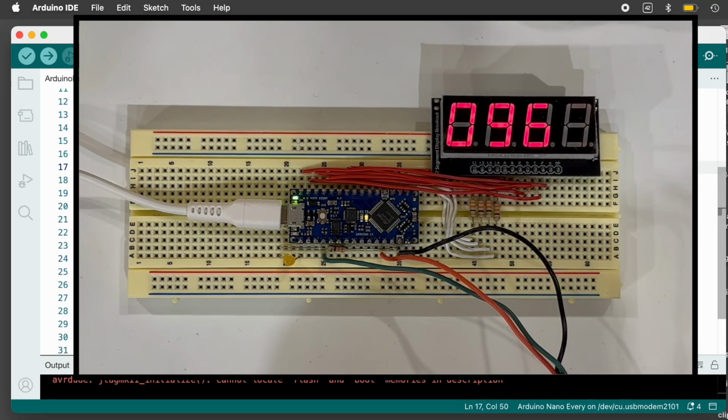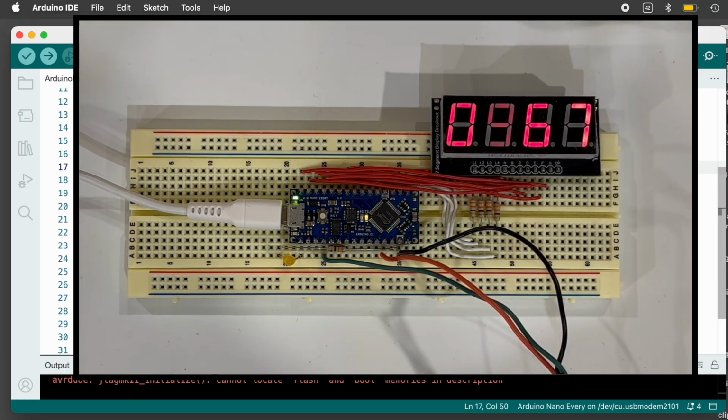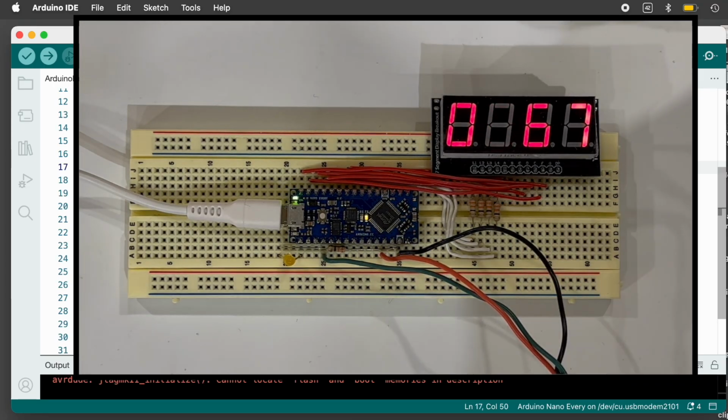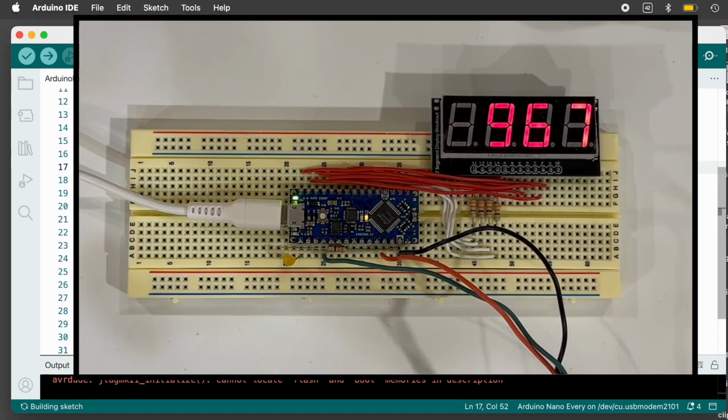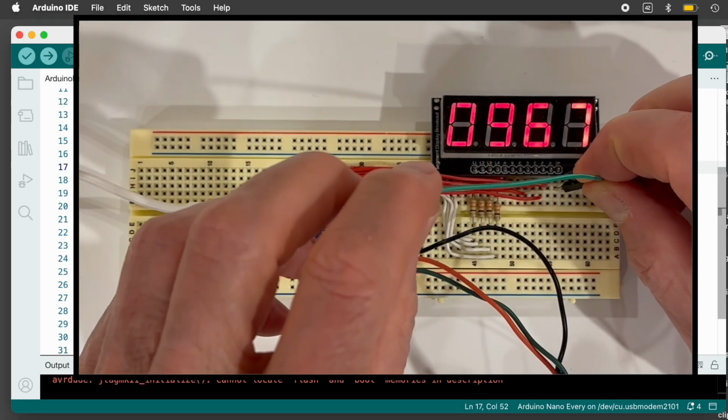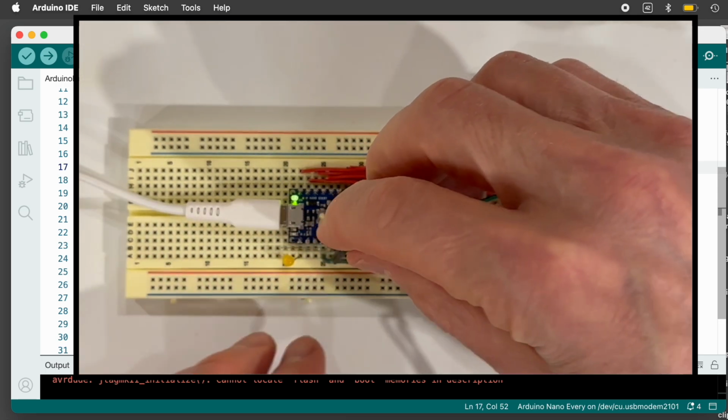This last parameter here is the pins for the segments, and I just did A through G. And now I need to use a pin. I'm using 13 for that LED. So let's do 14. That's free and available. And so I'll have to put in a wire. So I'm going to add a wire from here to...